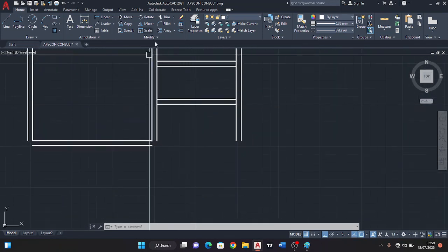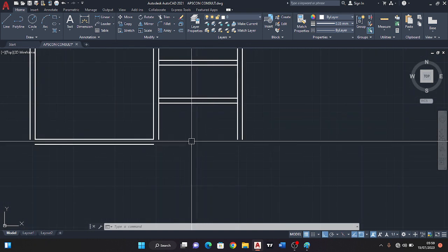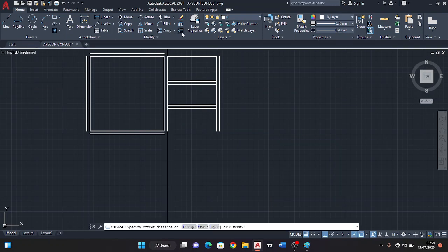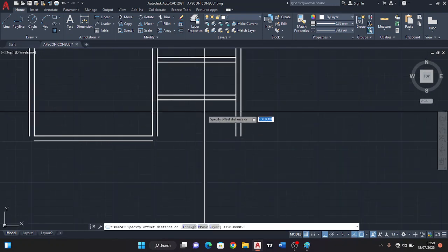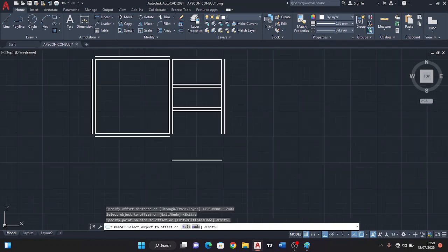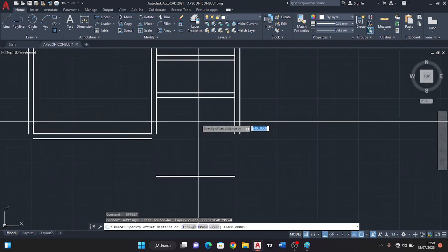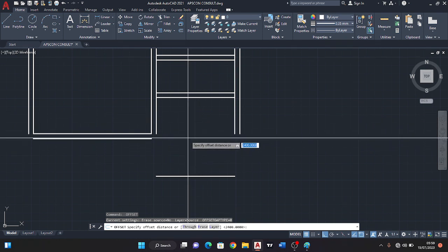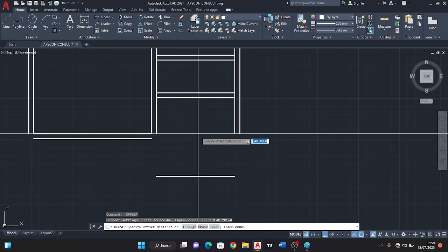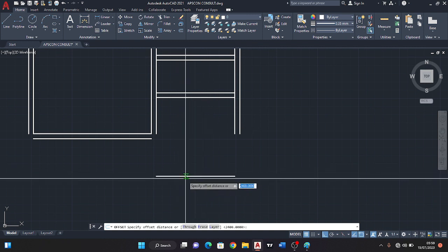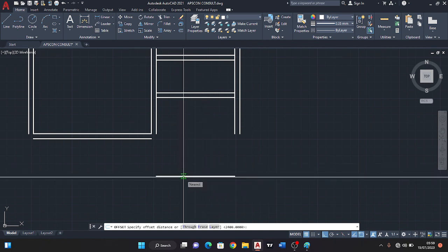So after then, I'm going to create my kitchen. Now this is my kitchen space. Now I want my kitchen space to be 2400 by 2400. This is a 2400 by, select another 2400, and yeah, I think that is what I wanted to create. I say okay. Now let me offset this place so that I'll be able to have my wall there. The thickness of my wall is 150.